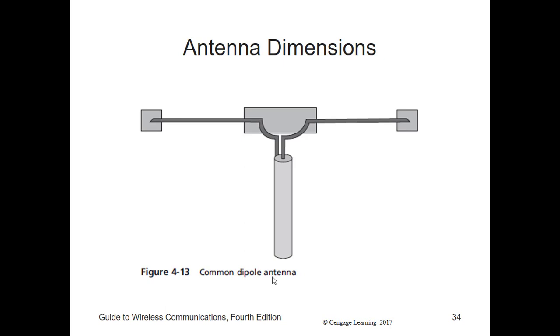To work properly, monopole antennas are mounted in such a way that they're practically sticking out of the ground or very close to it, or some other type of large structure that reflects the electromagnetic energy. Because the ground reflects the waves, it acts as a reflector, and this makes the monopole antenna behave like a dipole, rendering it more efficient. Alternatively, a monopole can be equipped with a large metal base called a ground plane to simulate the signal reflecting effect of the ground and increase efficiency.